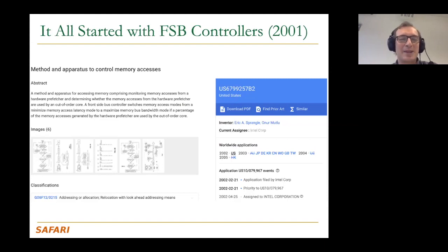Later, we did a lot of work on memory controllers. I'm going to actually briefly flash them to you. But it's good to think about the problems that you're working on initially, I think. And I enjoyed working on this. At that time, actually, it was not a traditional memory controller. At that time, in the 2000s, even earlier also, the memory controller was off chip, actually. So what you did have in the processor was a front-side bus controller. It used to be called front-side bus. Terrible name, I think. But it's essentially a bus that connects the processor chip to the memory controller chip.